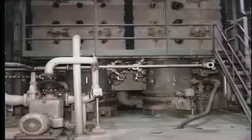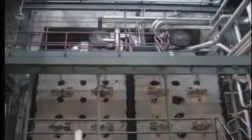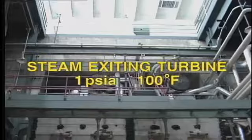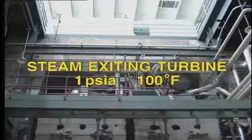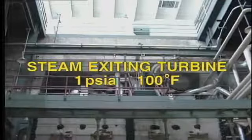However, if the turbine is of the condensing type, and this is far more common, then the steam exiting from the turbine will be at a pressure far below atmospheric, say 1 psi, and at a temperature of about 100 degrees Fahrenheit. Clearly, the amount of energy in the steam exhausted from the turbine is much less than in the steam entering the turbine.